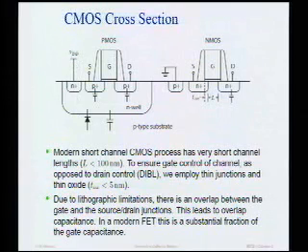But as we'll see in multi-stage amplifiers, a lot of times it's not very easy. I misspoke earlier. In a PMOS device, I can just connect source to my body, and as we'll see, that effectively turns off the body effect. But in an NMOS device, I don't have that option. Because this is a reverse bias junction, I have to ground all my body nodes. And that means that if I have source nodes which are not grounded, I will get the body effect. And we'll see that later on.